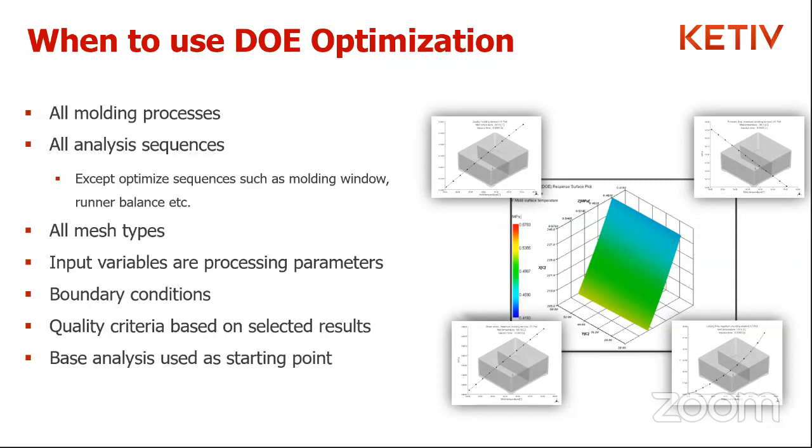There's no reason you wouldn't be able to start with something very abstract, run a parametric optimization, identify what the best geometry is going to be, and then run a DOE after that, identify what the best process for that specific geometry is going to be, and then go back and forth on each optimization routine to really zero in on your best part geometry, your best processing parameters for that specific geometry.